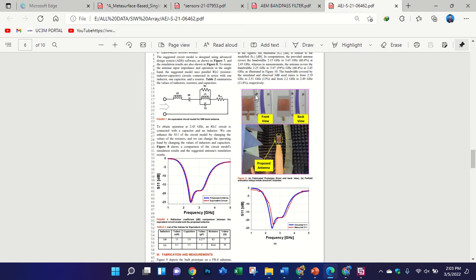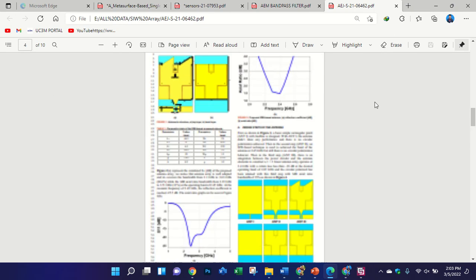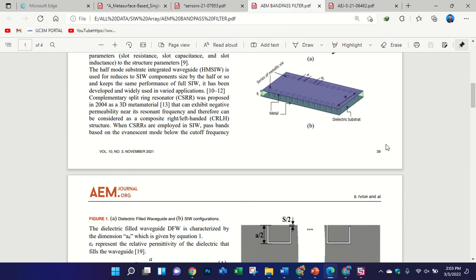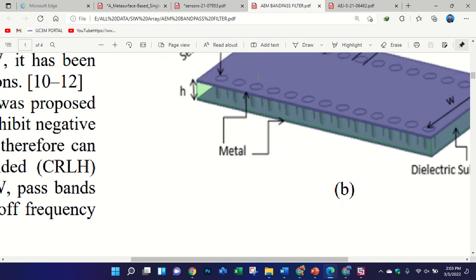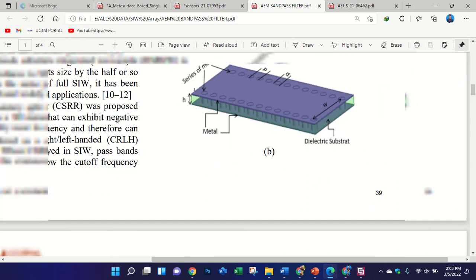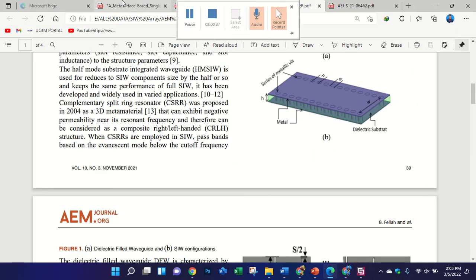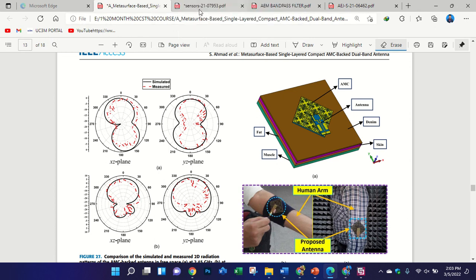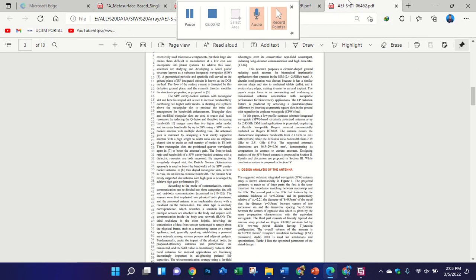And this hole is connected with the ground. Yes, that hole, you insert the shorting pin from that hole, and then you solder the patch and the ground. Okay, the shorting pin with the patch and the ground. So in this way you will find better results. So that's why I suggest you to use shorting pins. Okay.